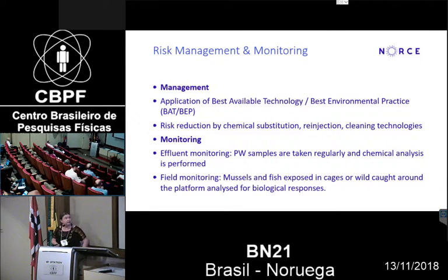Yeah, we also are involved in monitoring. So NORCE has been involved in the water column monitoring program for many years in Norway, working together with NIVA, where you have mussels and fish exposed in cages offshore. So you can feed back the whole risk assessment to actual monitoring and see if your actual predicted risk is the same as what you're measuring in the field with the biological organisms.